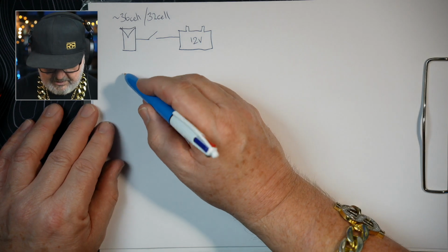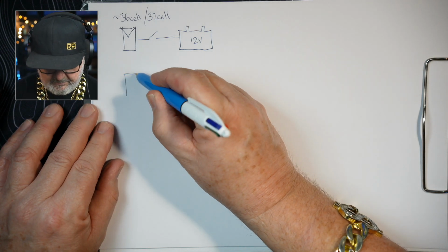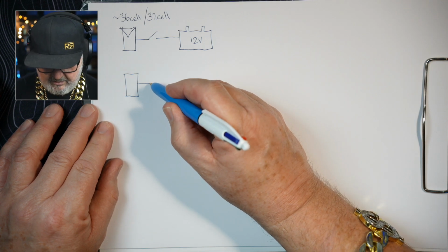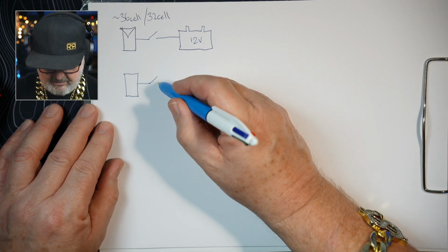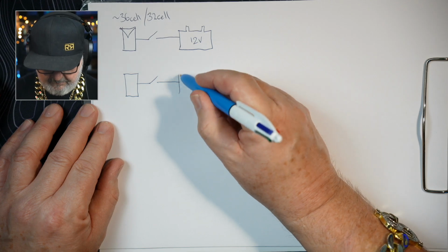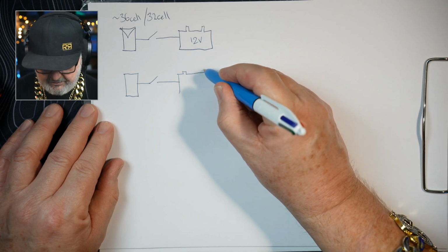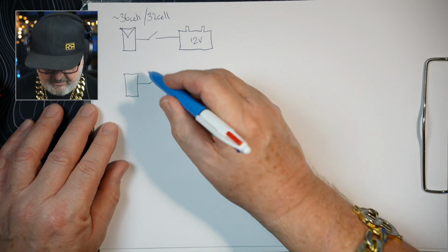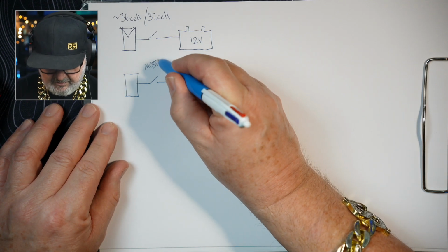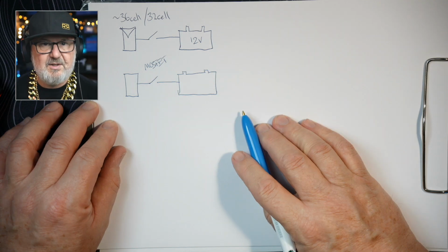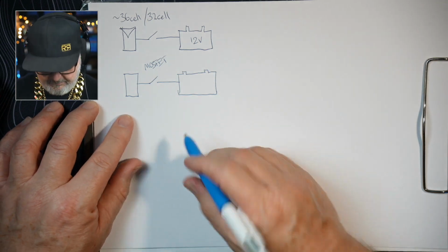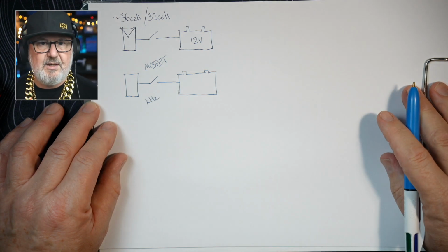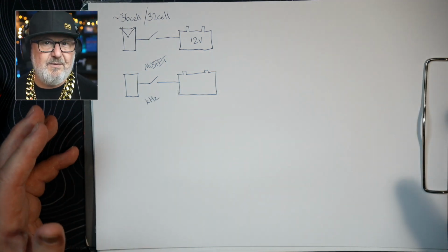Then along came something a bit smarter, which was still a switch, but it was a semiconductor switch. So this here looks like the same thing, but instead of a mechanical switch, it's usually a MOSFET, which is a semiconductor device, and it would be switching at kilohertz, so at really high frequency, on and off. Now, what's the benefit of doing this?